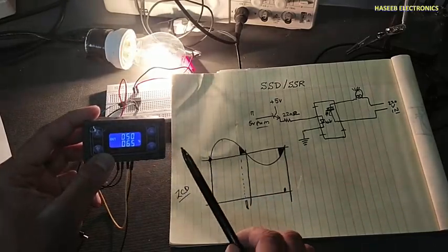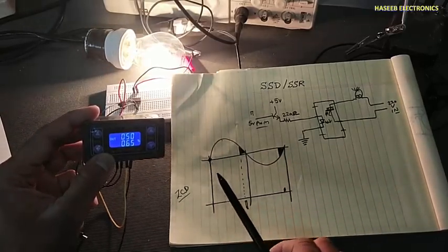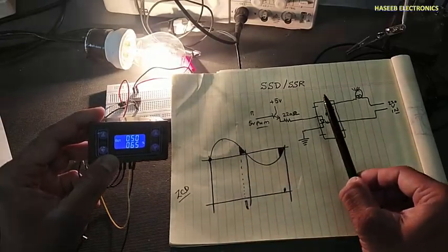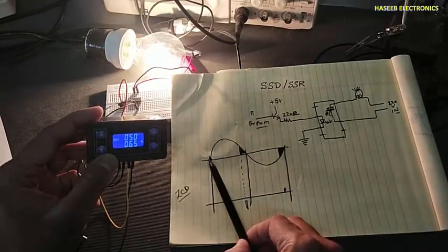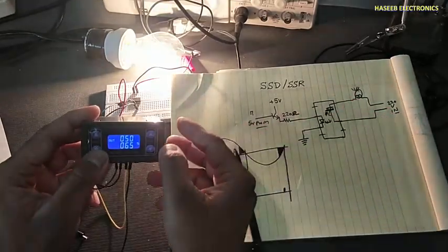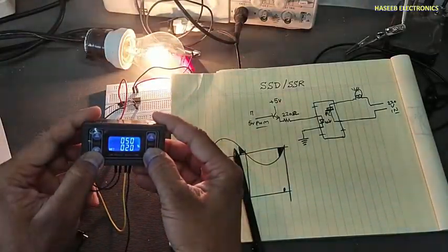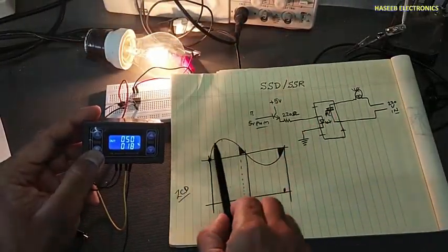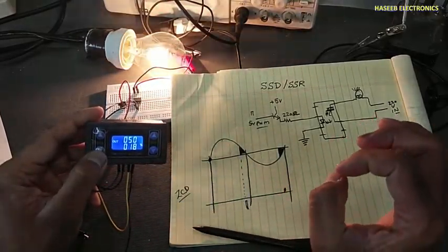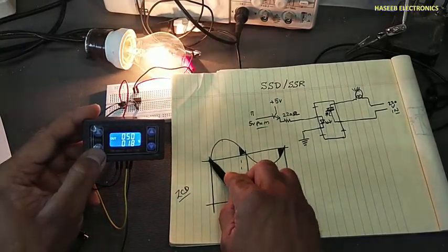But this time I am not coinciding with zero crossing. We need a zero crossing detector to take the exact voltage that we need. When the cycle starts from 0, after that we decide how much portion we need in the output. Because this time I am providing a signal at a random position. I don't know if it is switching here, here, here. But for exact, perfect use, we need to check the zero crossing position when it will start from 0.